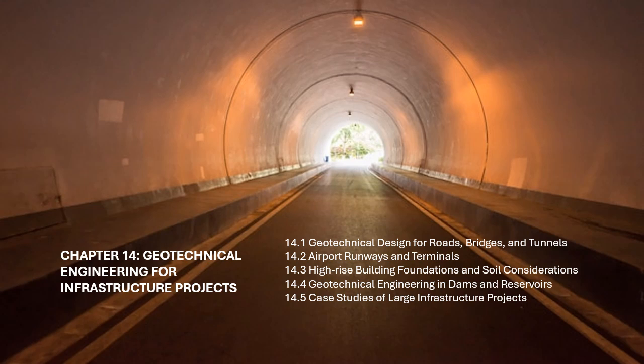Engineers must design the foundation to limit both total and differential settlement, which could result in cracks or misalignment. Ground improvement techniques, such as vibrocompaction or soil grouting, may be used to improve weak soils and reduce settlement.